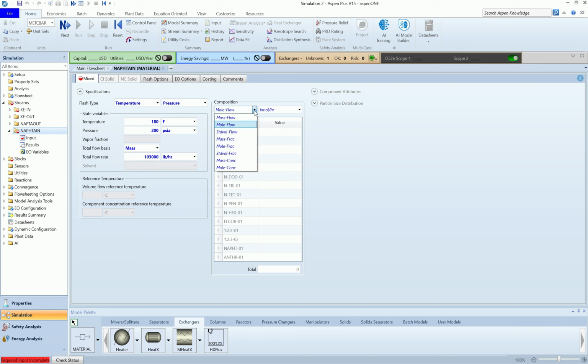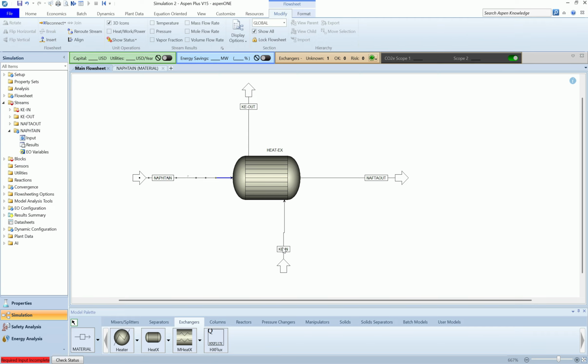Okay, and the mass fractions for the compounds are here. For the first three, we have these values in table 1, that summing must be equal to 1. Okay, let's check it. We can check here in this square, the total is equal to 1. So we defined the stream for naphtha in the inlet stream.